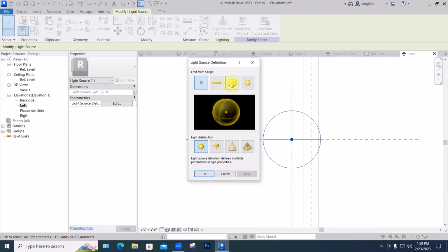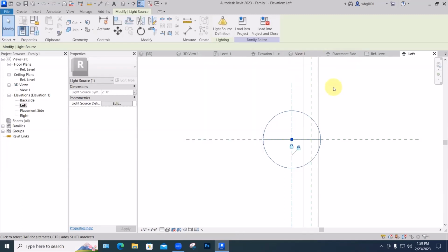Generally, the larger the light source, the softer the edge. And then we have to decide, will it be spherical in all directions, hemispherical, a spot, or one of these IES profiles? So those decisions need to be made. Will you have a shade or not? Are we going to see the bare bulb? If so, what shape and what material?